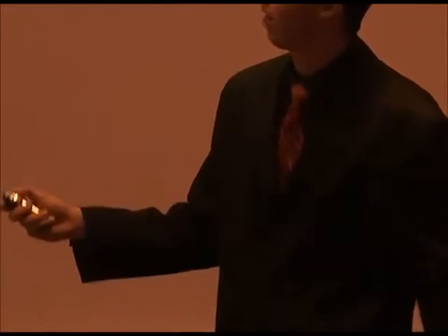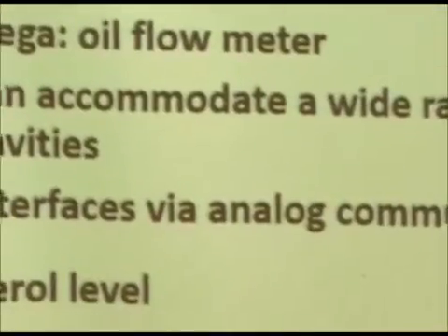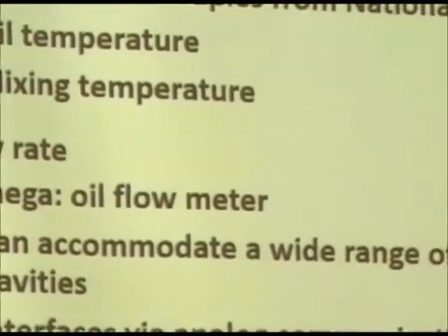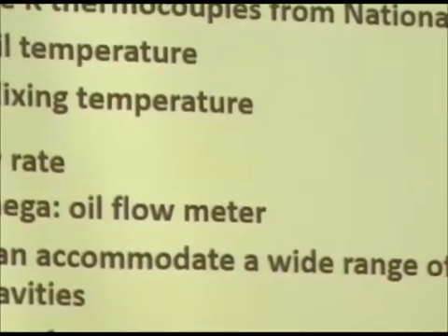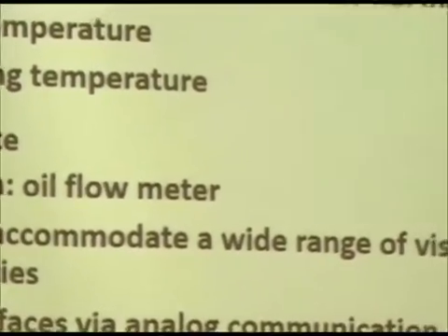One of the problems we have, actually, with automating the system in the future would be maintaining the glycerol level. As the state inside of the reactor is continually changing, and the glycerol itself is a very thick fluid substance, it doesn't flow continually. It builds up and then flows through really fast, breaks away. So it's hard to measure that depth. And so Dr. Parnas, the original maker of this design, himself said that it was very difficult to do depth measurements, it was very hard to measure that level. They ended up using a radar system that could do it. But we didn't tackle that challenge at this time.